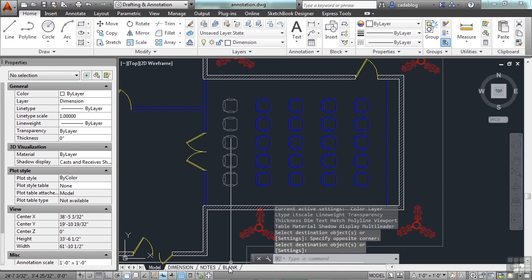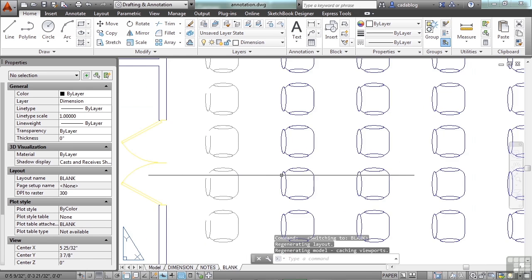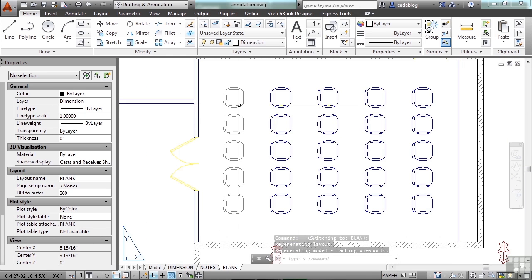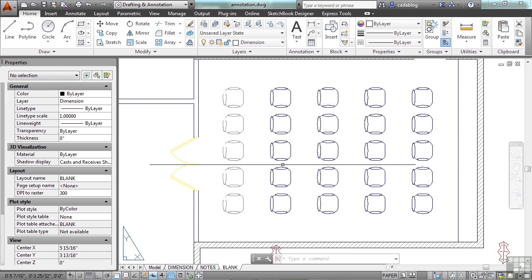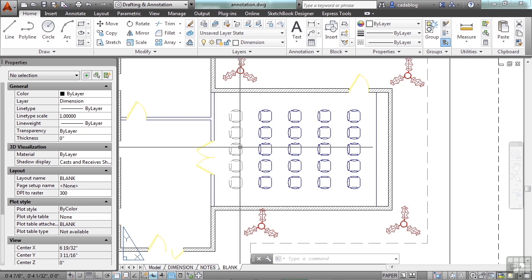So now when I go to my drawing, I can see that these chairs are a lighter color than this, and I need to do something with them. They're not highlighted like these new chairs are. Of course, then I can label them with a multi-leader or with some text and say, these chairs are to be removed. These are all new chairs. So you can do things like that with your layer manager, with your different layers and with blocks, and you can do them very quickly.